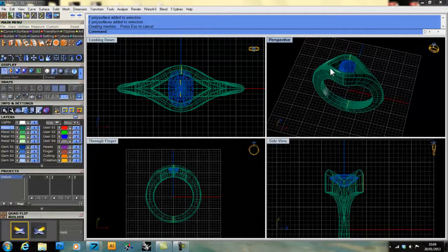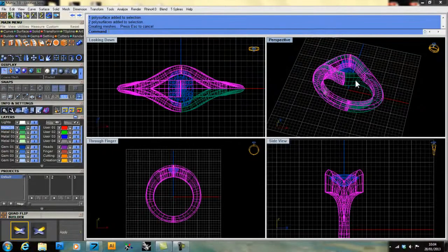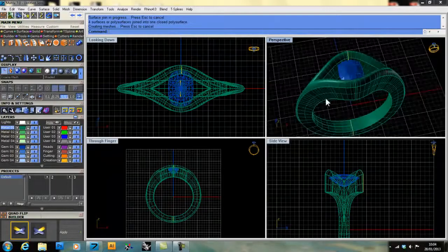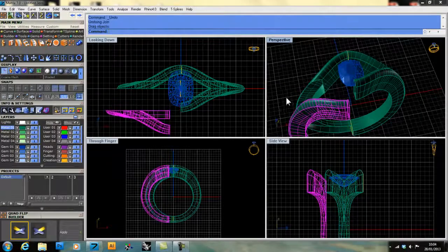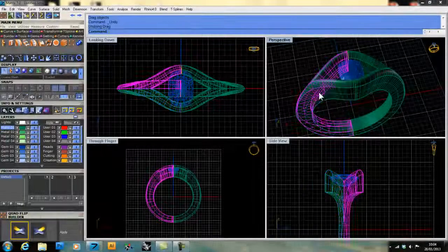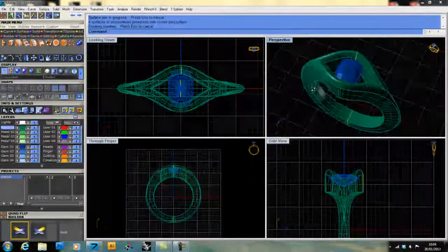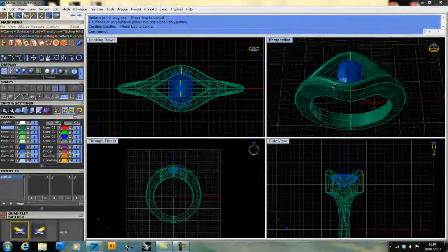Now all I will have to do from here is simply rejoin the shapes together, just by selecting the four and using the Join command. The reason why we do that is because this creates incomplete and open shapes. So we need to join them together to make them closed again. It's one of the side effects of working with a surface modeler.